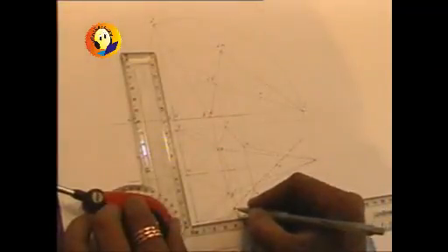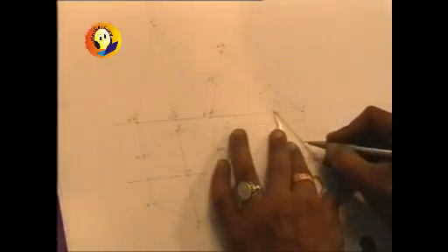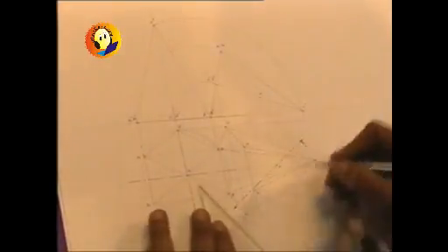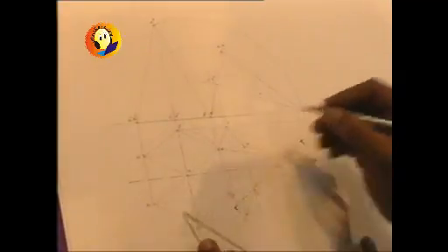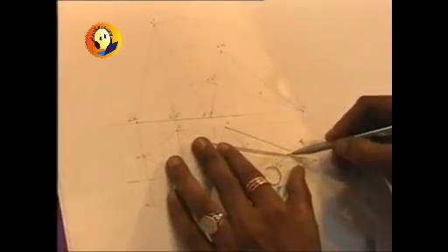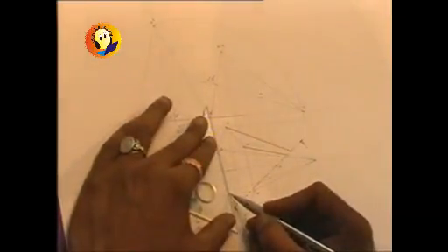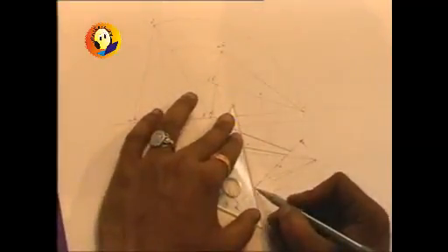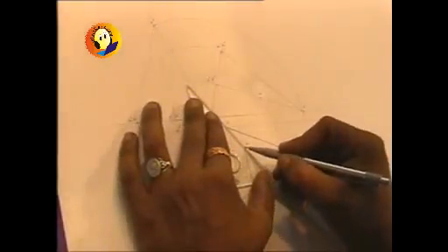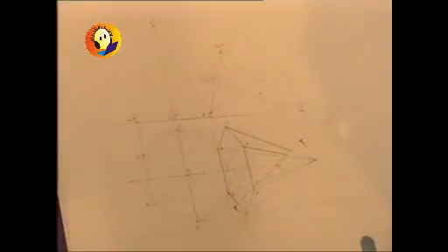So the cutting plane has been shown, and make the ends of that cutting plane thicker, and also indicate the portion of the solid which is retained by the arrows. So we want to retain the remaining part, and so that can be darkened now. The portion of the top view, once the object is cut, which is remaining, should be darkened. And so what you can see over here is this portion will be made dark. So this is the portion of the solid which is retained.